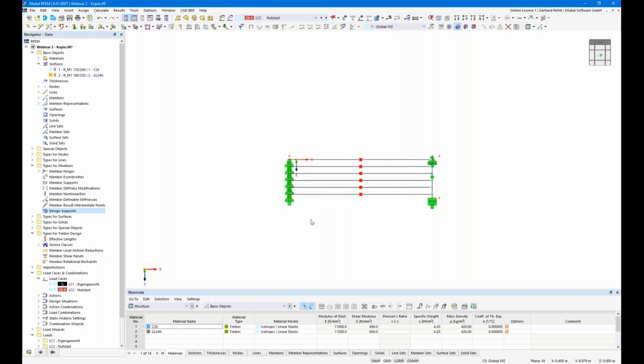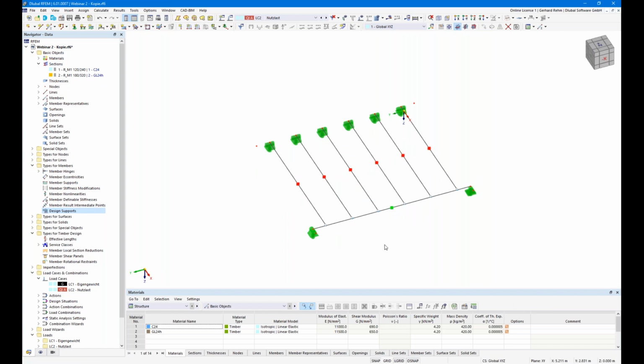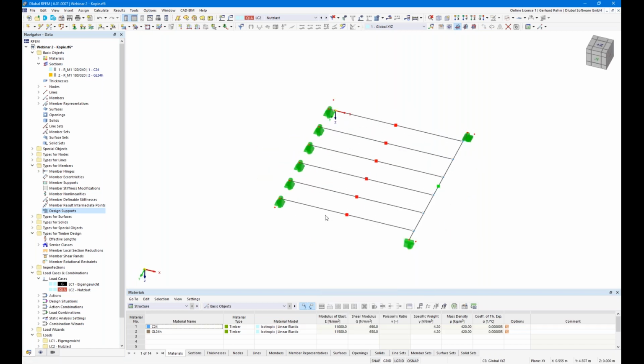So we have started to implement this feature, and it's finished already for general cases, but in more complex structures, for example, when a lot of beams come together in one node, it's quite tricky, and we need to find a solution to know where the beam is supported and where the bearing area is, and so on. But I will show you this feature on this floor. It's a floor with a few beams supported on a downstand beam. So there is no rigid support here along this downstand beam, of course. So we have a semi-rigid support for these beams. Okay, so let's start with the beams.